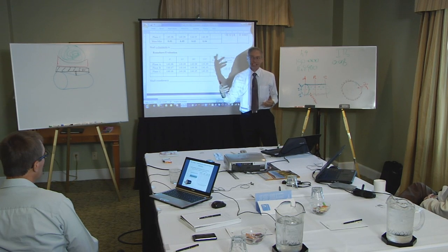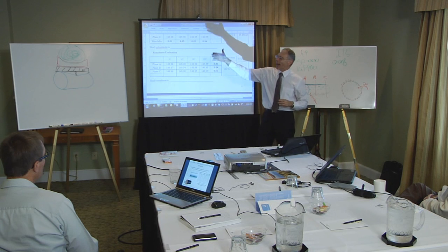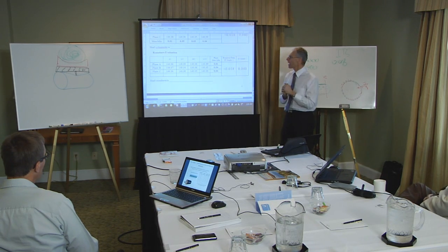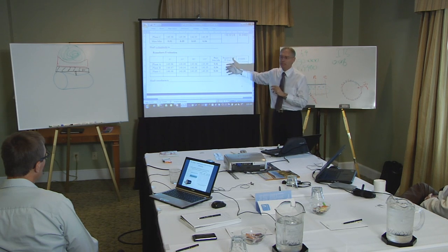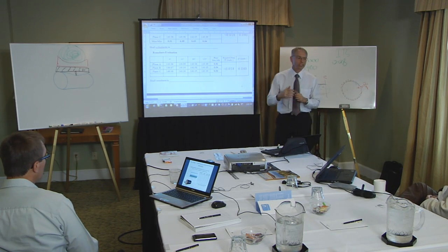What's the guy thinking? How can you keep doing that year after year after year? Obviously the guys maintaining that didn't understand what it was saying, because nobody measured this. Nobody ever measured this until the guy came in from the bearing manufacturer and said, please tell me how round, how cylindrical that shaft is. Should have been the very first thing that was done.